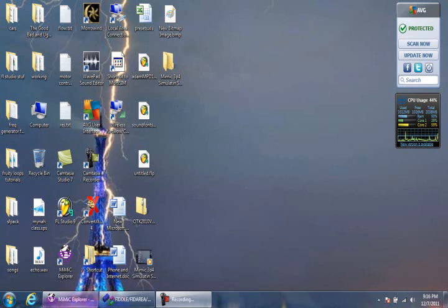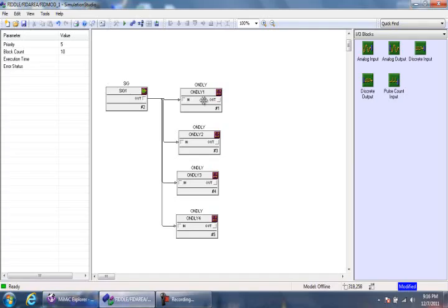A question came up about a particular block. Somebody wanted to know what signal hold duration does when you feed it different values. So what I did was create a whole bunch of on delay blocks, and I simply changed their durations. And I'm feeding it a square wave with a period of 5 seconds and an amplitude of 1.